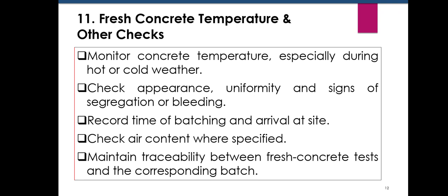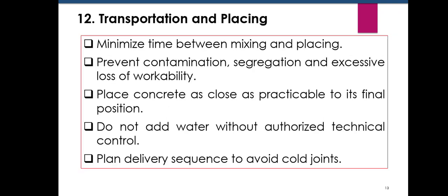Next is transportation and placing. The time between mixing and placing should be minimized. During transportation, we must prevent contamination, segregation, and excessive loss of workability. Concrete should be placed as close as practical to its final position. Uncontrolled addition of water should be avoided. Placing sequence should be planned so that undesirable cold joints are avoided.